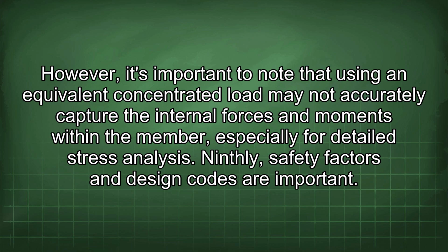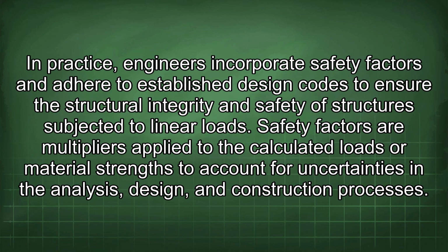Ninthly, safety factors in design codes are important. In practice, engineers incorporate safety factors and adhere to established design codes to ensure the structural integrity and safety of structures subjected to linear loads. Safety factors are multipliers applied to the calculated loads or material strengths to account for uncertainties in the analysis, design, and construction processes.